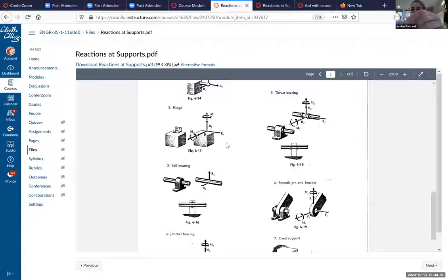What about a rotation? Certainly these 2 pieces can rotate about each other along the axis of the hinge, but otherwise they cannot rotate in that direction and they can't rotate in this direction. So if you look at the reactions of a support on a hinge, you see there's an Rx, Ry, and Rz representing the forces, the translational motion that it could resist. And then it also has a rotation about the X and a rotation about the Z, because that is preventing motion in that direction. However, around the Y, these 2 pieces can rotate relative to each other.